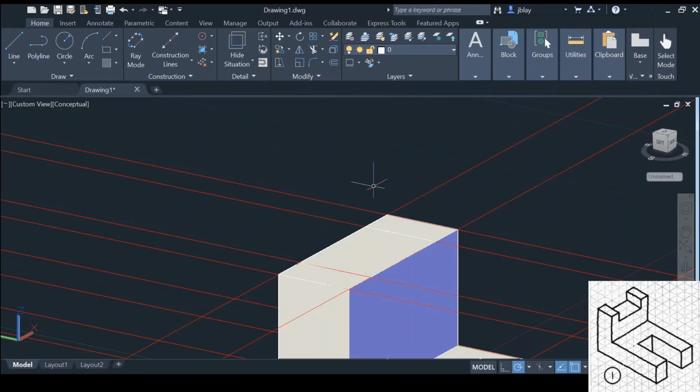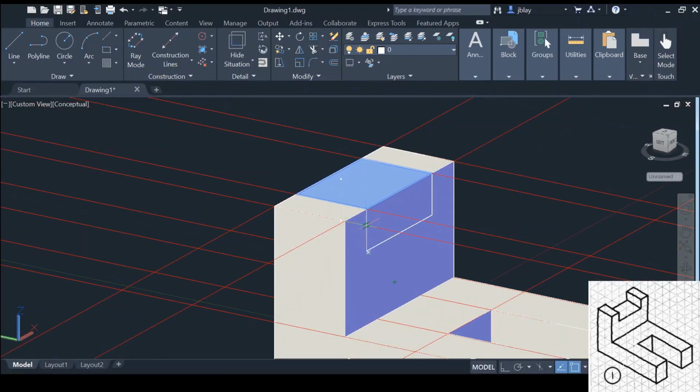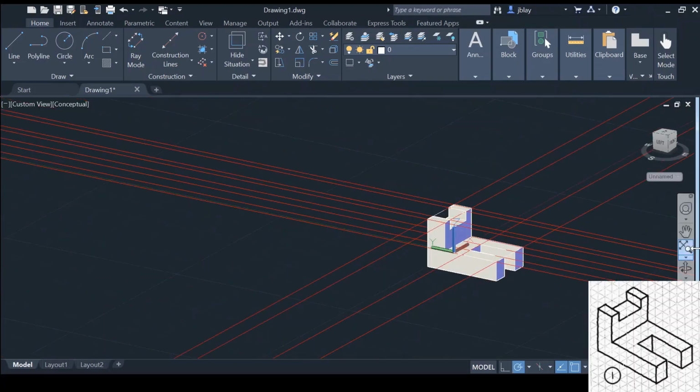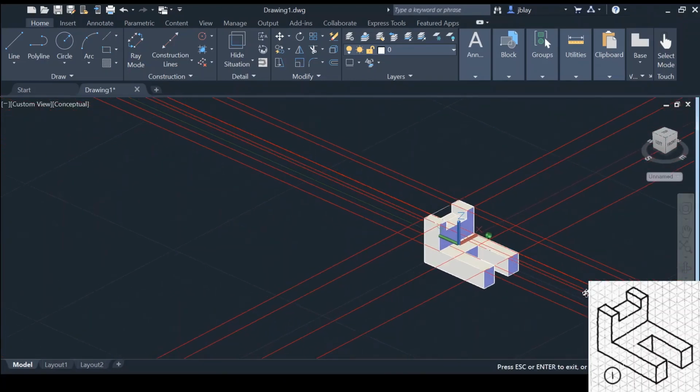Okay, and then we need to press pull. So again, I'm typing in press pull, and I'm going to select inside the bounded area of this rectangle. Now, how far does this need to go? Let's see. It goes down 1 unit, which is 1/4 of an inch. So this isn't going to be all the way through. We're not just pulling all the way through. We actually need to type in the value, 0.25 inches, and we pull through. And now we have our finished shape.